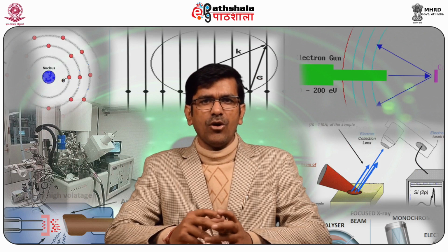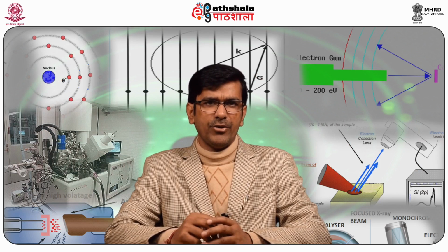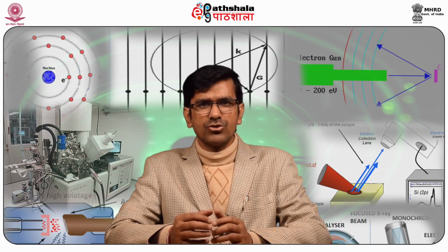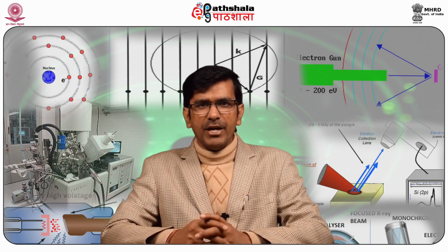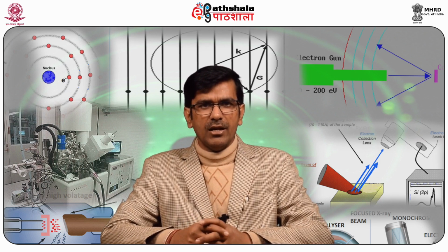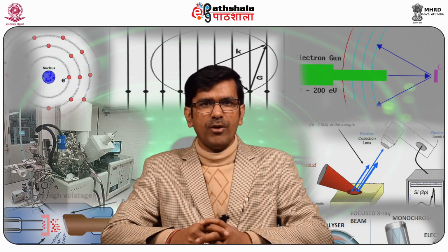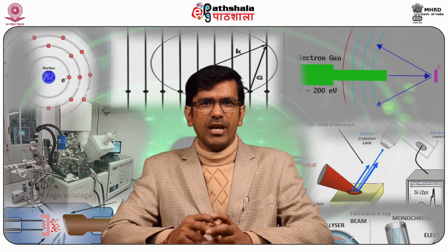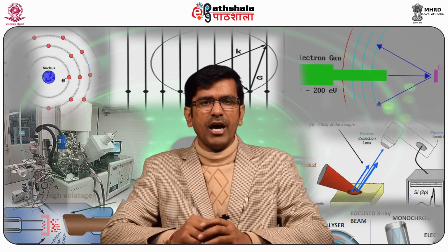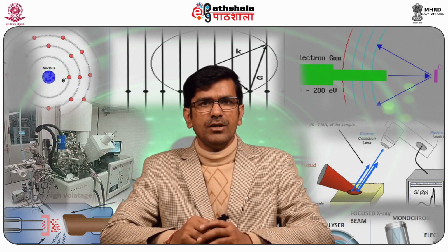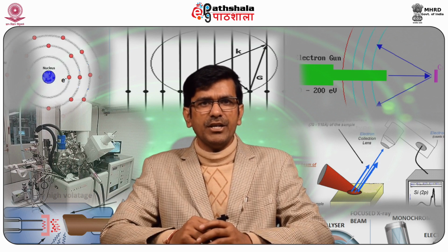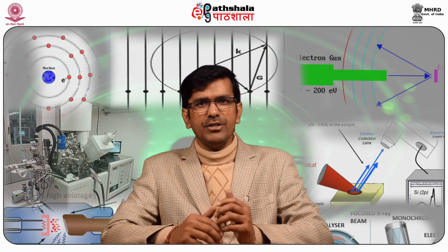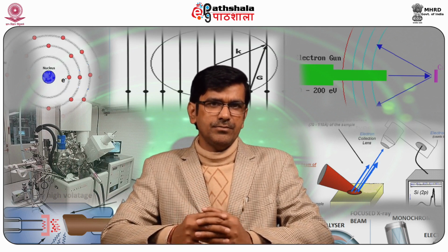As you know, among all the microbeam techniques available nowadays, secondary ion mass spectroscopy, or popularly known as SIMS, is most versatile. By combining in situ microbeam measurements with the high specificity and sensitivity of mass spectrometry, the SIMS has the capability to detect most of the elements in the periodic table with a high dynamic range. SIMS is also a well-established technique in the semiconductor industry, where it is used to measure the concentration of dopant elements.